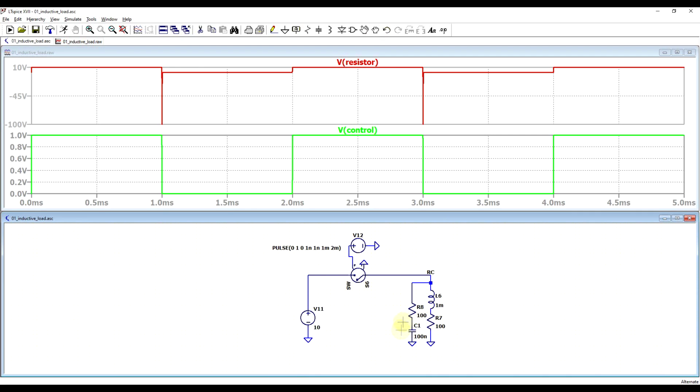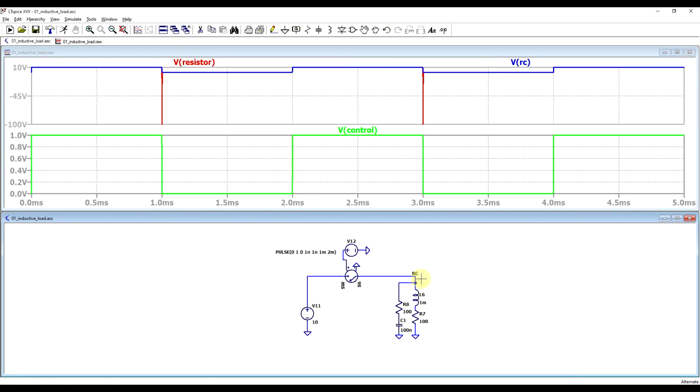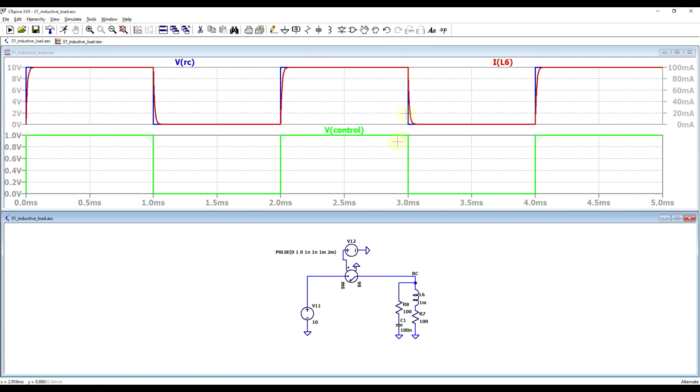So the next best thing is to only connect your extra resistor when a transient is occurring. So during your steady-state DC operation, you don't want to have this load connected. To achieve this, you can connect it through a capacitor. So with the second circuit, this RC version, we are able to absorb the inductor current into our resistor through a capacitor. And this way, we no longer get our large negative spike. The only drawback here is that again the inductor current doesn't instantly drop to zero, but it takes the time it takes, based on the values of the RC circuitry.